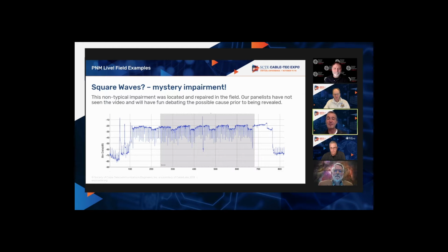So let me tell you where I have seen something similar. Then we'll watch a video and we'll all exchange notes about who was right and or rightest. I have seen some field meters, for example, that have multiple tuners, and the tuners will sample and then interleave the measurements to increase the speed. If you can manipulate two tuners at the same time, you can go twice as fast. And then occasionally the front end of one of the tuners will become damaged.